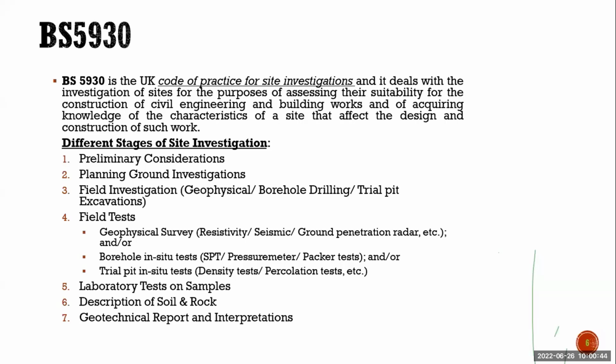So what kind of soil and rock properties are we getting? All this study, before you start the investigation, without doing anything on the site, is called the reconnaissance survey. Then preliminary investigation: based on your reconnaissance survey, you decide to keep this many test points, and do these tests to get an idea.